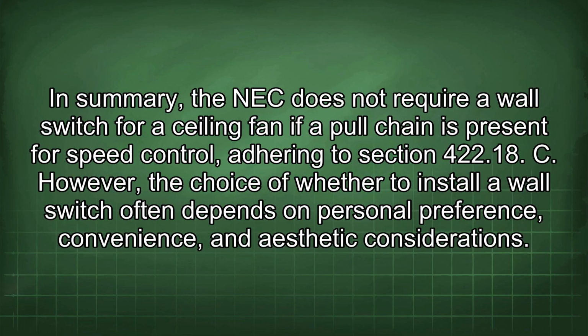In summary, the NEC does not require a wall switch for a ceiling fan if a pull chain is present for speed control, adhering to section 422.18. However, the choice of whether to install a wall switch often depends on personal preference, convenience, and aesthetic considerations.